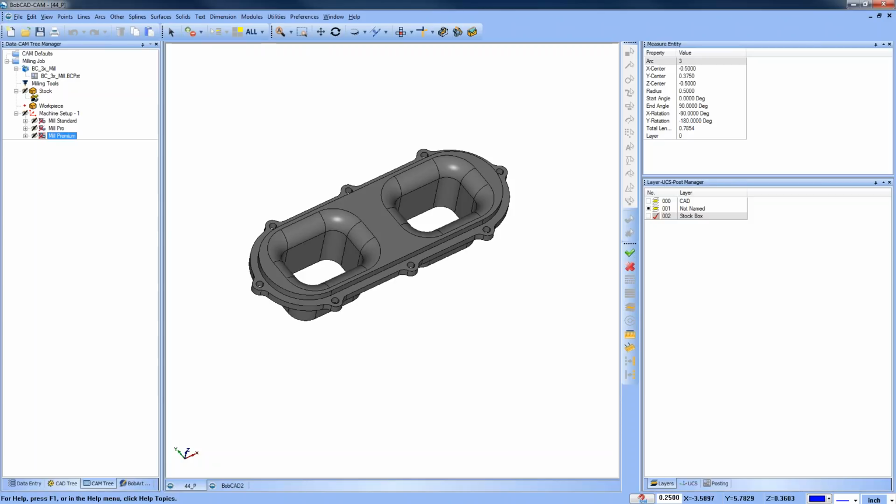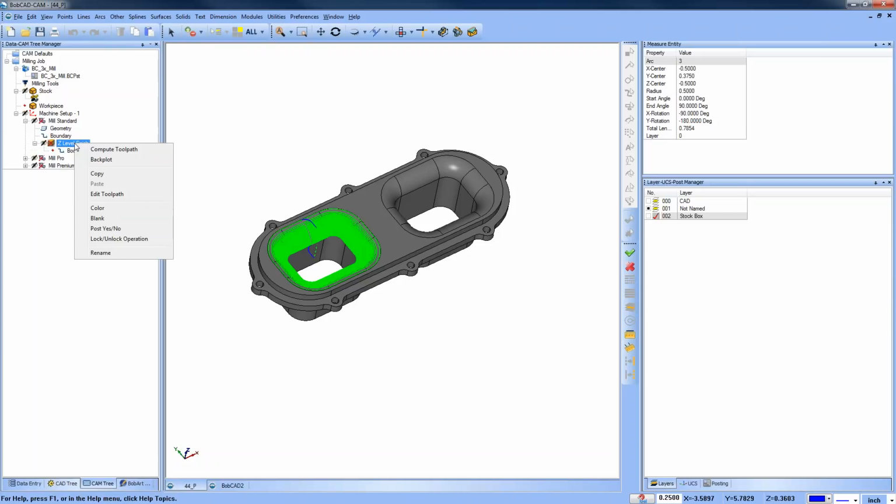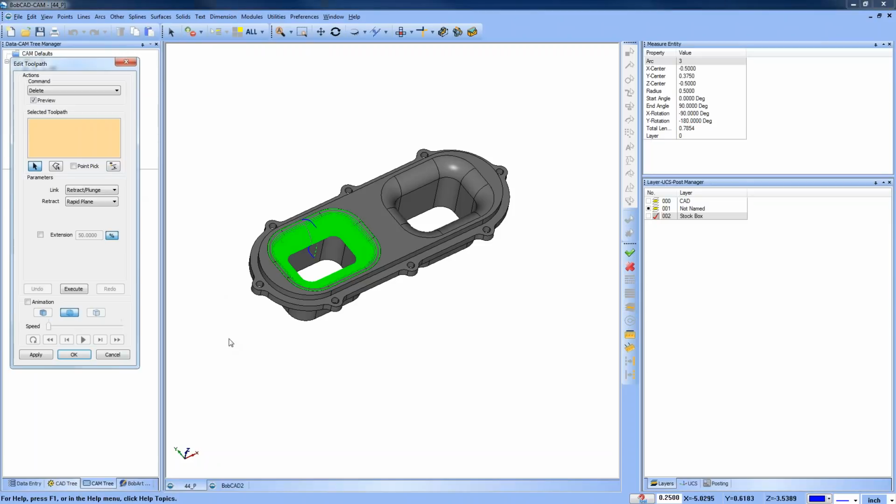Let's see here, Grant. Can you build onto an existing toolpath? I'm not sure what you mean. I'm curious of what CAM software you've used in the past. One of the things that you may be talking about here is all of your toolpaths. If you right click, you can go to the toolpath editor. This editor has a bunch of different functions in here to break, move, and edit your toolpaths. Okay, I understand what's going on now. The workflow here is going to be a lot different for you than it would be in some of the classic versions of the software.